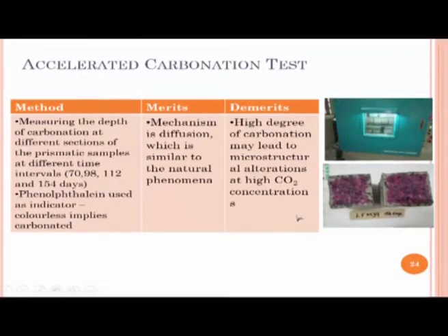Now of course, when you have a lot of carbonation in the accelerated test, that increased level of carbon dioxide may completely change the mechanism by which carbonation happens. In real life you are only working with 0.04% in natural carbonation. Here you are working with 25, 50, 100 times stronger concentrations of carbon dioxide. So you may not always get the same chemistry of this phenomenon that you observe in real life. That may be one of the disadvantages of the accelerated carbonation test.